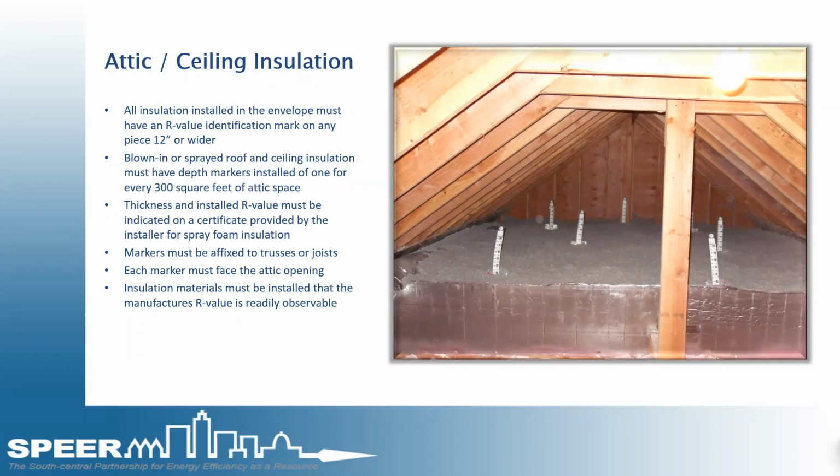Here we see a picture of the yardstick markers being stuck up. They're not attached to anything. Probably by the time humidity hits that, they're all going to be laying down in the insulation, not observable for inspection. It looks like they propped them up with something, so they were still able to see those at a final, but they should be affixed to something so they don't sag during construction, to know that the insulation has been blown properly.